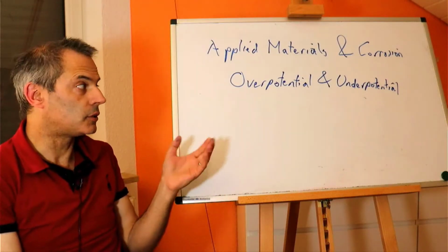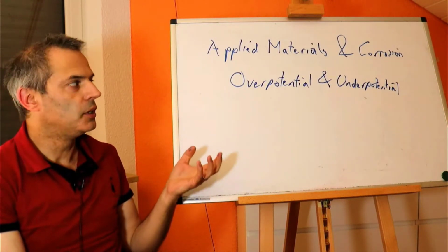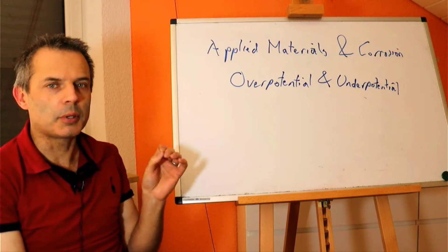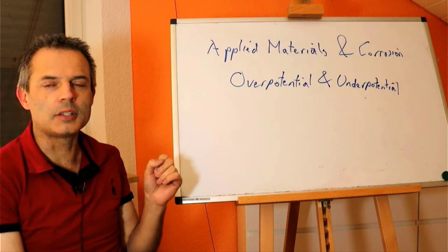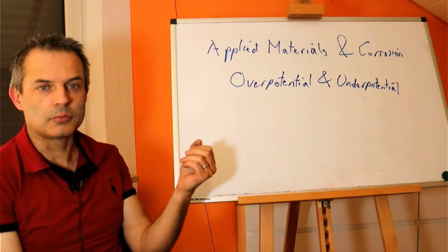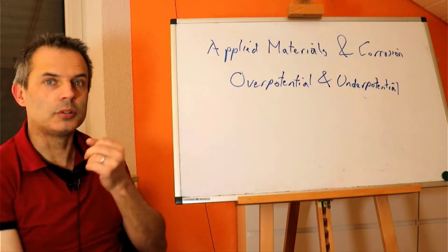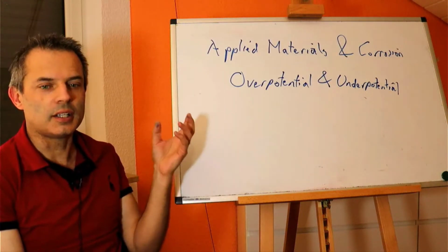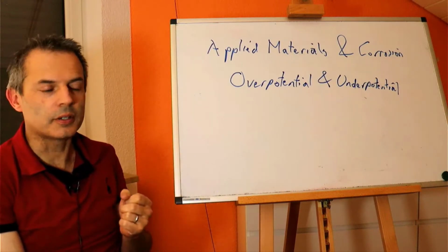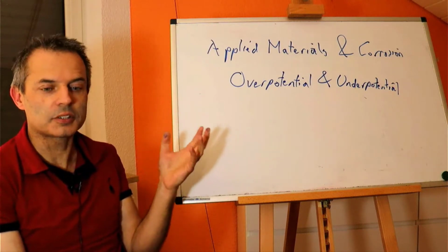This phenomenon is actually quite common and it's really useful. It's also a problem in some conditions. So it's really useful because obviously the tin, even though it is thermodynamically unstable and should form tin 2 plus ions, it's blocked kinetically by the activation energy of making hydrogen, so you can still make a tin can out of it and put sour fruit in there and it still doesn't poison you. There is a problem, obviously, as people found. If you use other metals, then you can cause it to corrode much, much faster and then poison everybody.